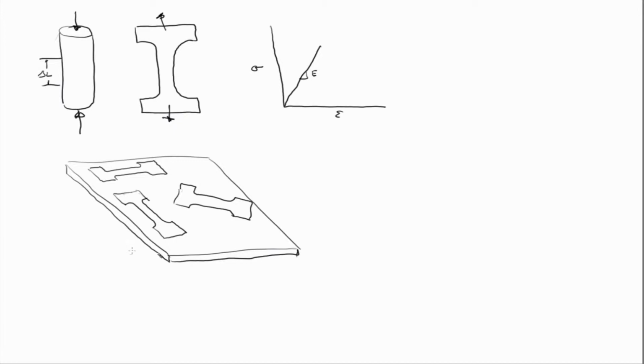Okay? But the problem is everything we covered up to right now assumes that the material is elastic. Well, up to how much strain is most material elastic? Just like a steel, maybe more like 0.2%. So a fraction of 1% strain, and the material is no longer going to be elastic.